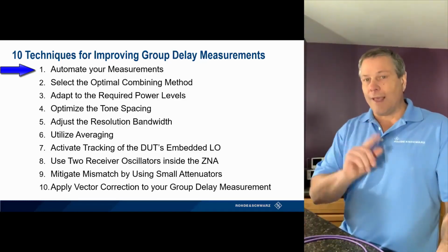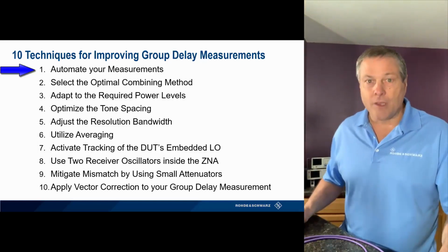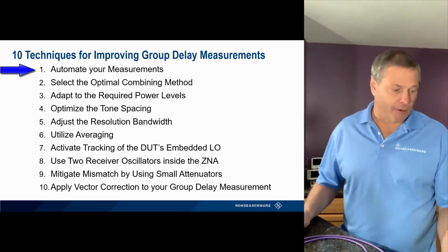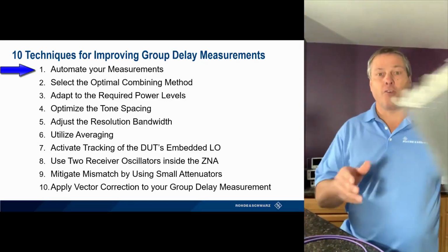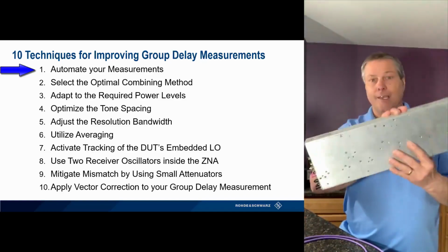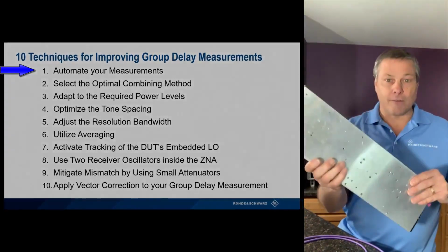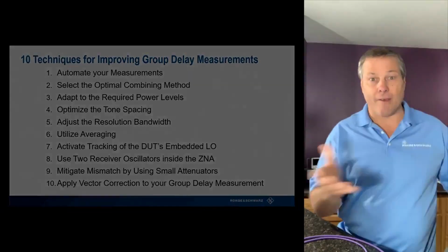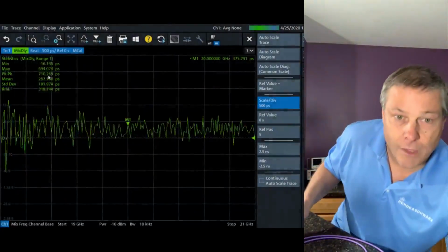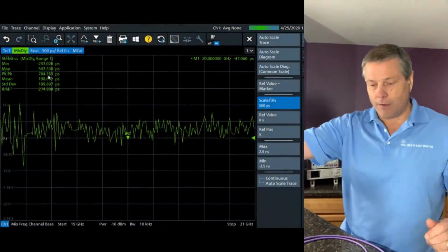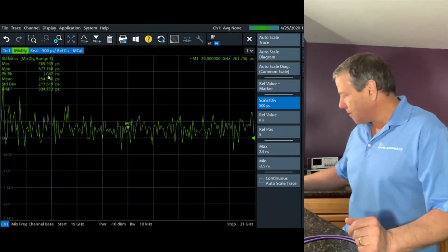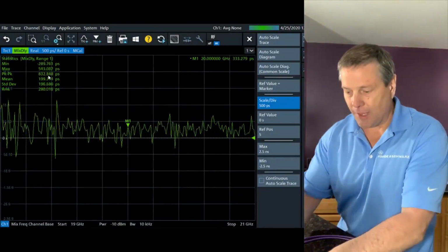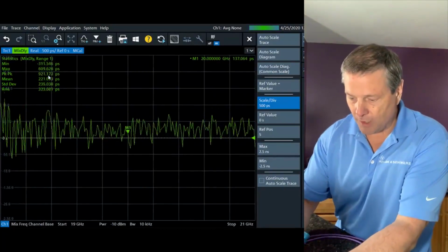Okay, one last thing for this video before we wrap it up. So far, we did not connect to the device under test. As I said, we are going to measure something like this MyTech satellite block down converter. So far, we've set up the channel and we calibrated, but we haven't made any measurements. So let's do that. Now I have another box like that set up here.